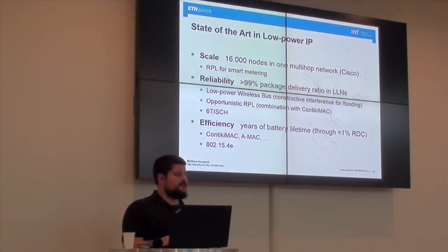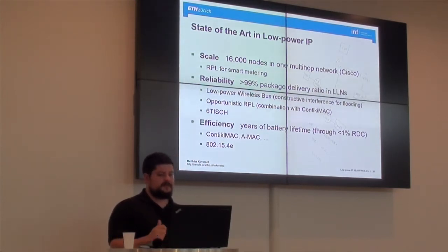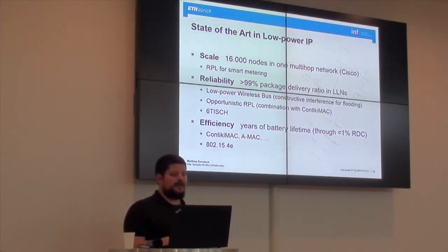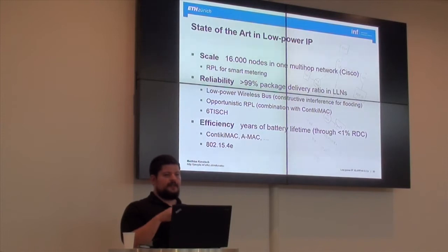Reliability, speaking of it, what you can achieve is more than 99% delivery ratios, although you have lossy links in this environment. There are some new results from research, like the Low-Power Wireless Bus, for instance, developed by some colleagues at ETH Zurich in the electrical engineering department. What they use is the capture effect and constructive interference to flood the whole network. If you have multi-hop communication and do the timing right, within half a microsecond, you can just overlap the sending wave, and you can go in waves to really flush this in a few milliseconds, and basically have this feeling of a bus. You have multi-hop communication, but you just put it on the bus and everyone can read this information.